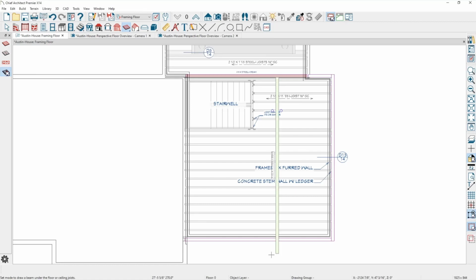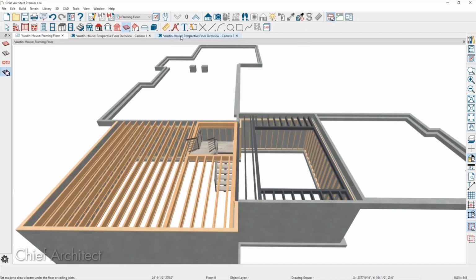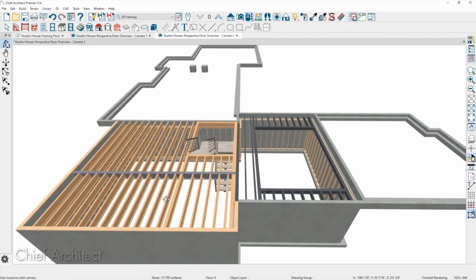So let's just assume that I cut a new beam across the top there, right? And that's probably going to come in line with the other joist. If I need to move it down the thickness of that joist, then I can push that down 14 inches, or whatever it turns out those joists are. Then you can either copy that or draw another one, whatever works easiest for you.